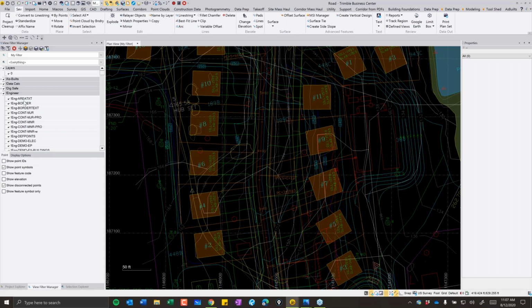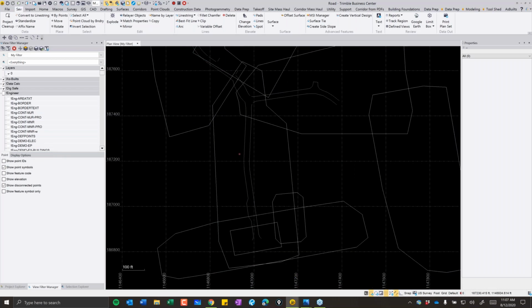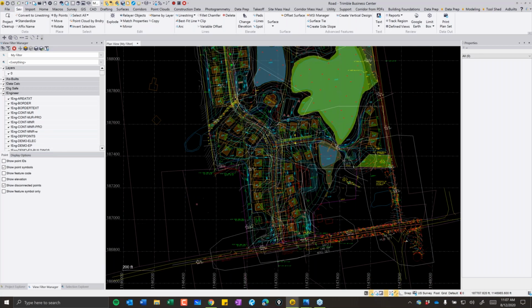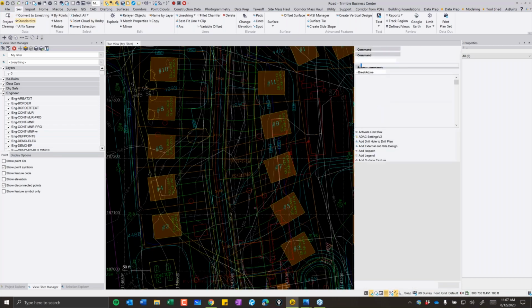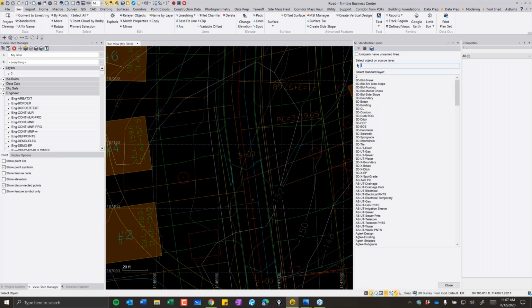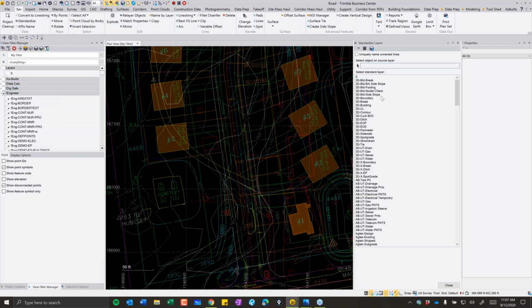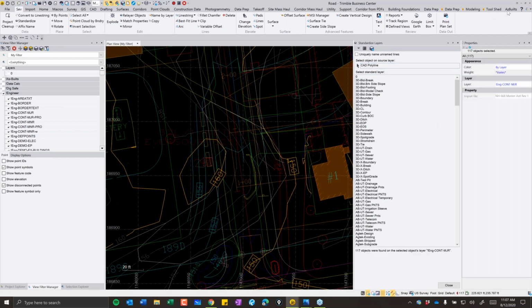And then I like to do everything in layer groups. Makes it very easy to turn everything off, and then I can see, okay, this is stuff that I've already prepped. So by utilizing the layer groups, that's very valuable. So we'll just go through, and my biggest tool I use when I first bring in is the standardize. And I'm just going to turn this off. So I'm just going to grab some line work.